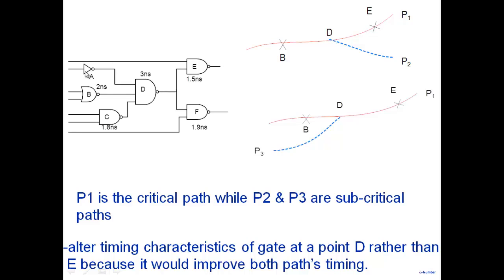And at that point of time, I'll have to run timing analysis again. After doing the layout, I'll have to do a STA, static timing analysis. And I may find I'm not meeting the timing constraint. So what do I do? If I'm not meeting the timing constraint, well, I can do something to the layout. But sometimes, no matter what you do to the layout, you can't fix it. You have to go back to the logic level or the RTL level and say, no, I was trying to use a simple adder, I have to use a carry look-ahead adder.